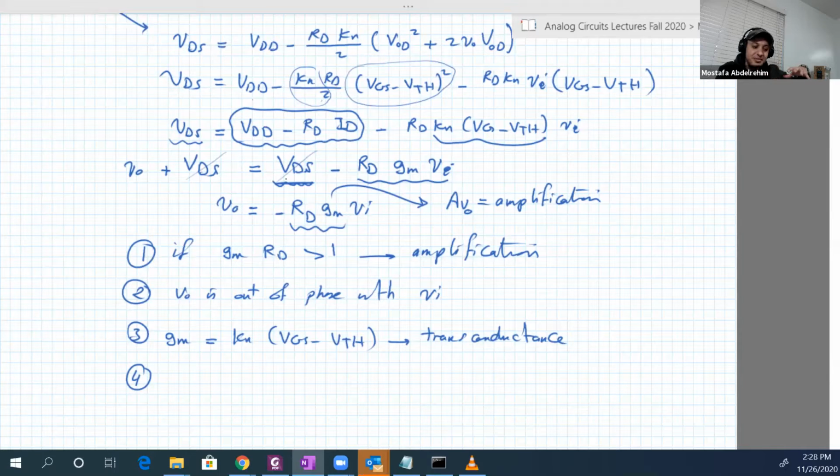So basically, another assumption that we can make in this analysis is that, again like the BJT, we can solve the AC domain by itself, canceling all DC sources, and solve the DC domain by itself, canceling all AC sources. So the AC and DC domains are decoupled.